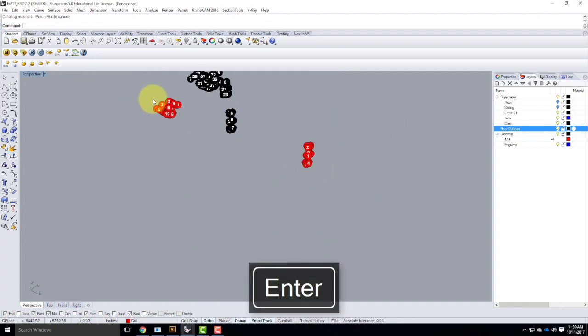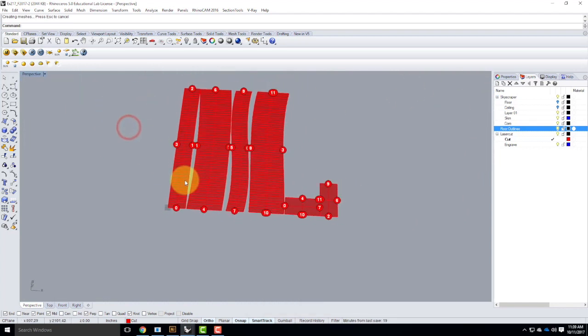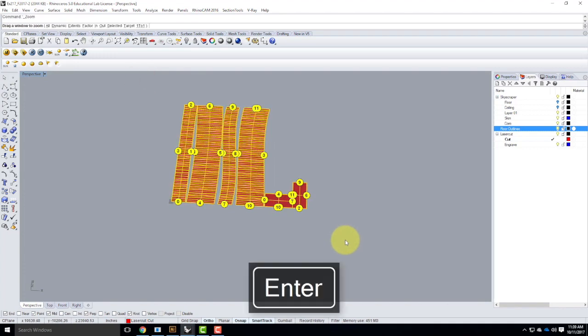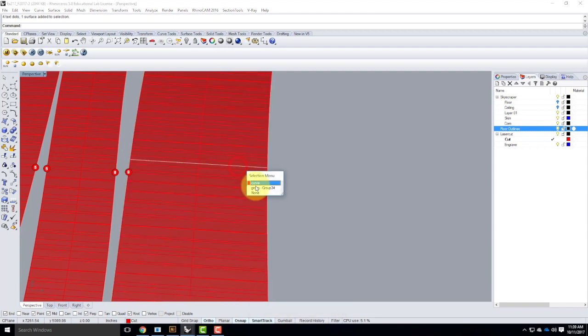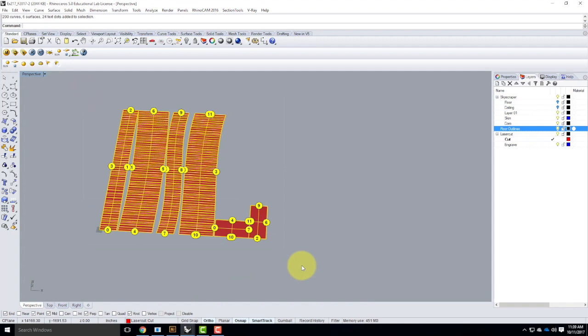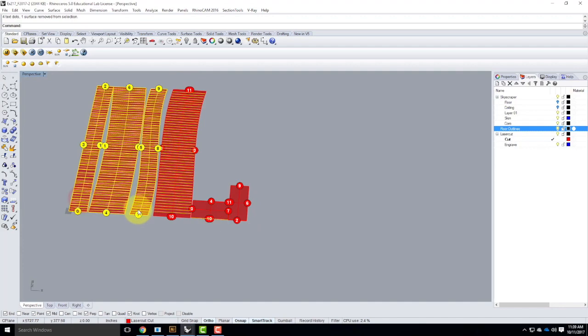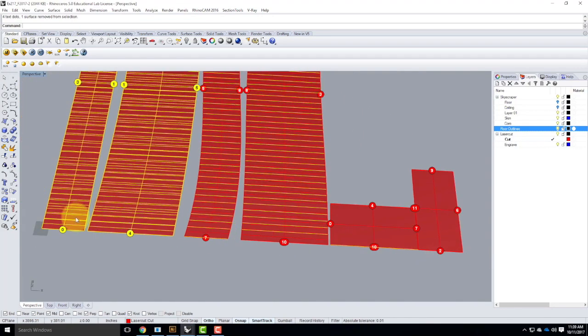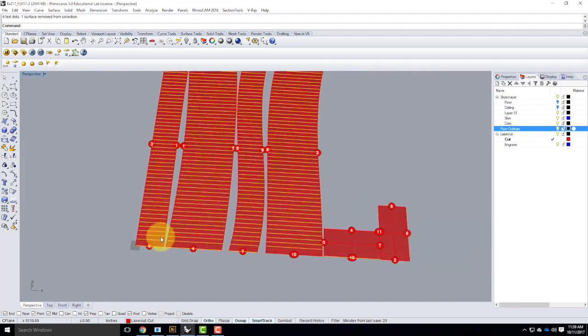okay, there's my numbers, there's all of my pieces. But as I look at this, hold on a second here, there are a bunch of individual little curves that represent each floor that were unrolled with the surfaces. So I could use all of those pieces as score lines to represent all the floors in my building. So let me deselect the surfaces for just a second so you can see all of them. There we go. There's all those floors.